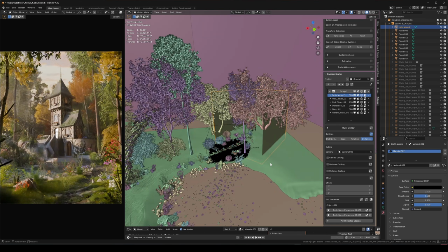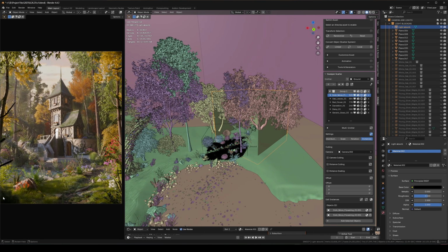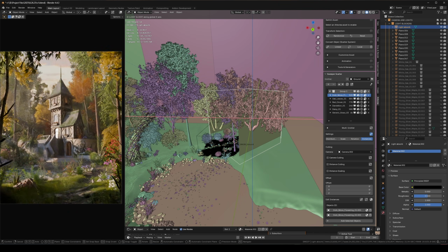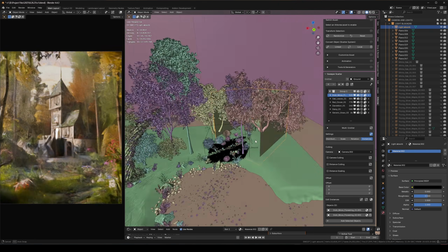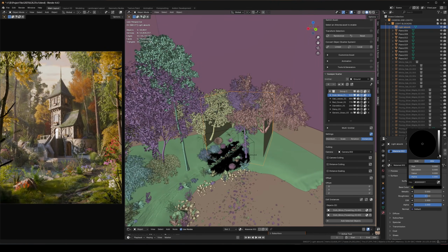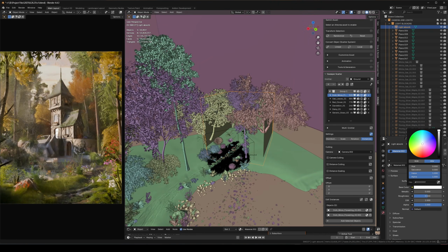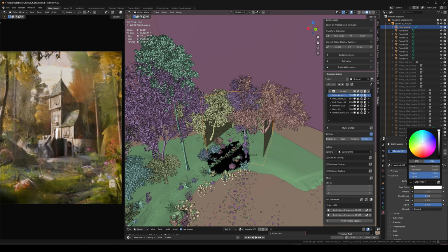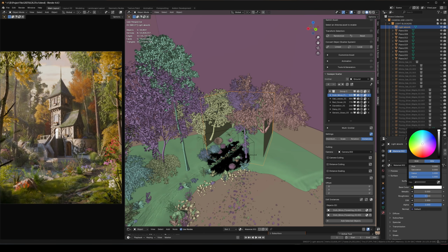But in this case, and in most cases, I try to just make it so it darkens these corner assets and assets right next to the camera without actually seeing the wall of shadow. And yeah, this color just depends on how dark I need this. Right now it's kind of subtle, but you can see pitch black on the corners. But if I bring this up, it slightly lightens a little bit just because light's going into the cube and then bouncing right back on the back sides of those assets.